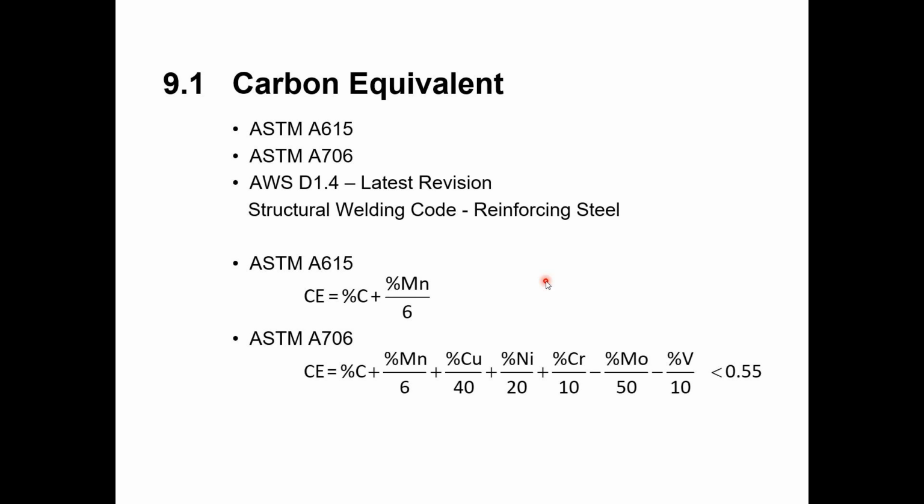And then it would be a pretty rare circumstance, but let's say you got some rebar with a given carbon equivalent of 0.75. Anything 7 to 18 has to be heated to 500 degrees, which would be pretty difficult to do and maintain at that temperature. One thing to note: if you get mill certs from your rebar supplier and they are not giving you chemical data, not giving you any of these chemical compound percentages, such that they're not giving you the carbon equivalent, but they're also not giving you the information to calculate it yourself, you have to assume worst case.